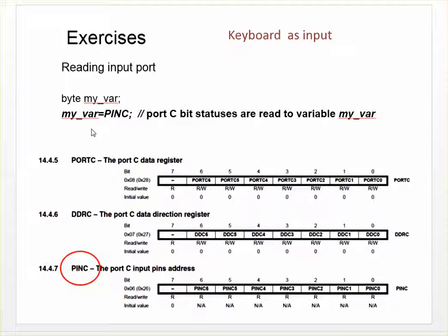Okay, earlier we defined our port as an input port, and then the question is how to read the input statuses from the input pins. In our processor we have this PINC register. That is the register where we can read the input pin statuses.